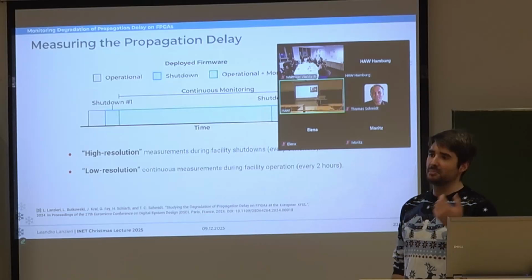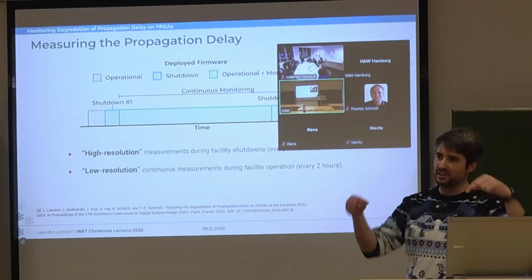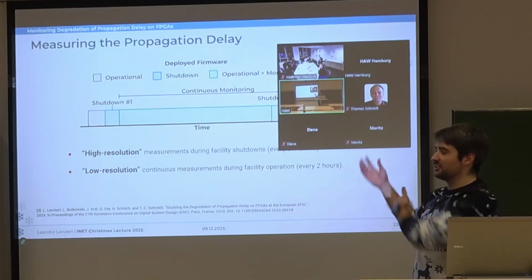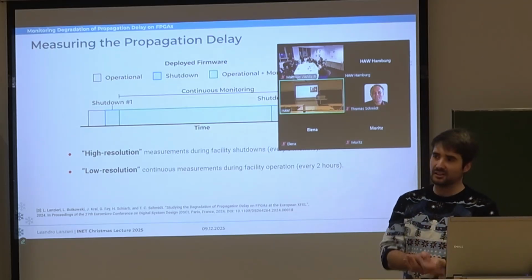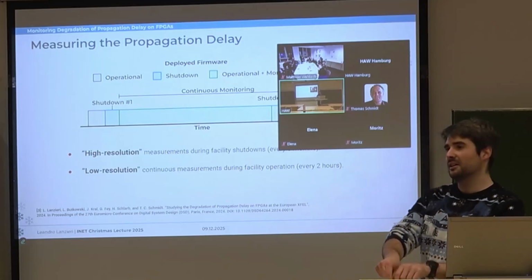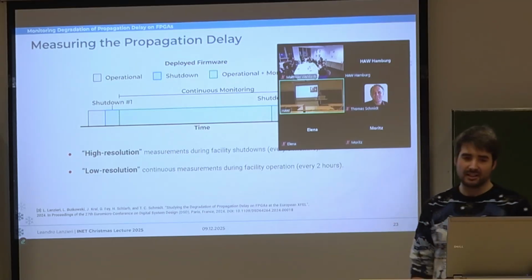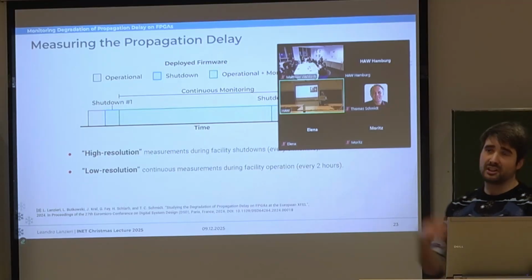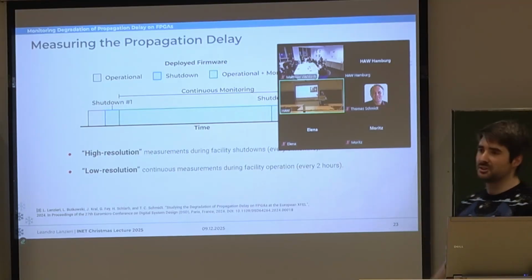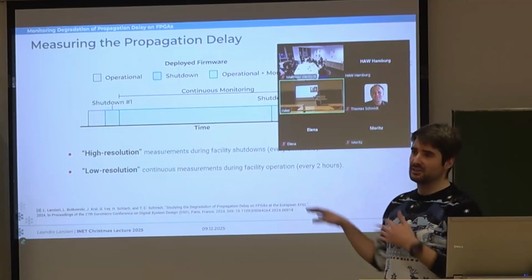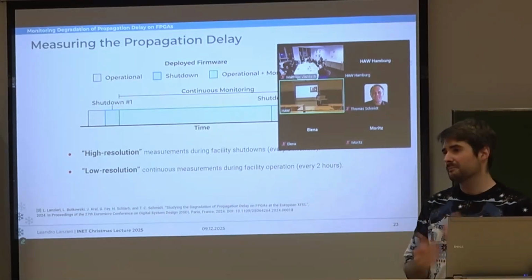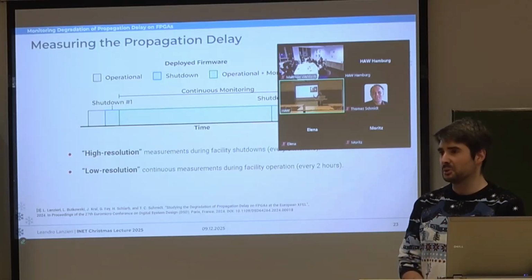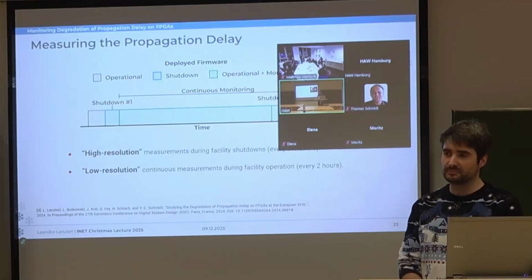That's a good indicator, but it depends on the device how you can actually get to measure that, right? In SRAM, you need to do all these tricks with a startup to actually look at the thing, because we can't put the scope and measure the particular nodes, right? And so that's why the approaches are different, but I think they try to measure not the same thing, but a similar effect, in different ways. So yeah, I would say that's a good central point, I think.